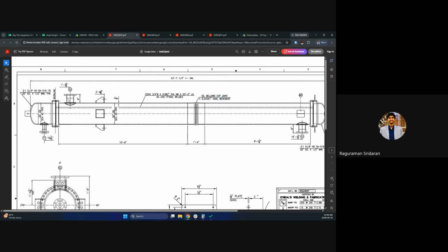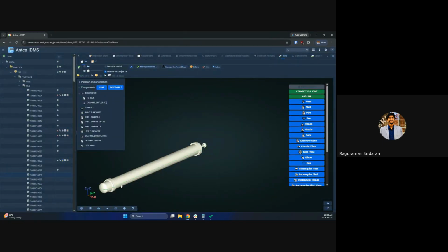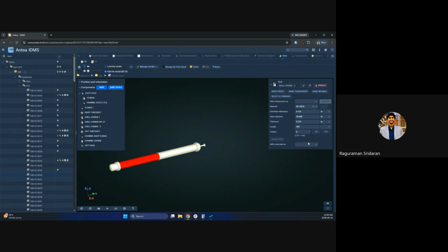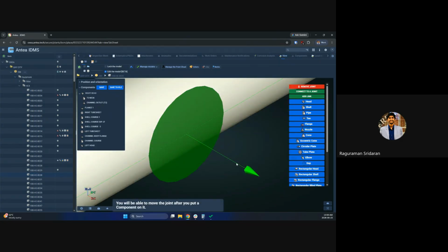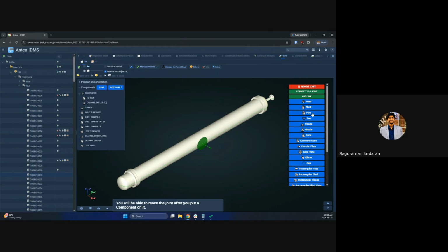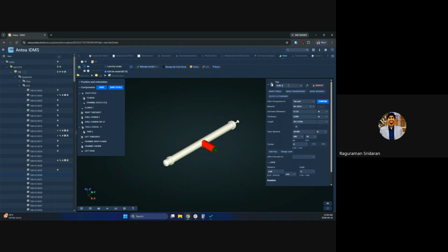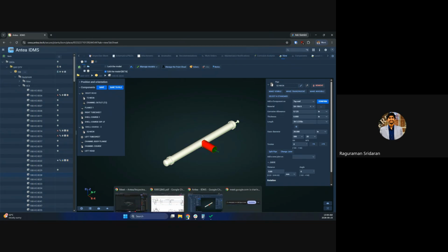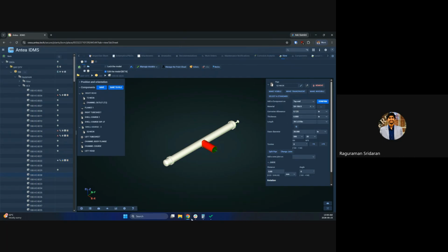So this is the branch that we are going to create. So let's select. It's going to be on the shell course 2 or 3. So we select outer wall. This nozzle is going to be created on the outer wall. As I said, we are not creating any internal components, so it's going to be on outer wall. So we select outer wall and say neck, or the pipe. That's the neck for S2. Select, save this information, and SA106B, that's for the neck.